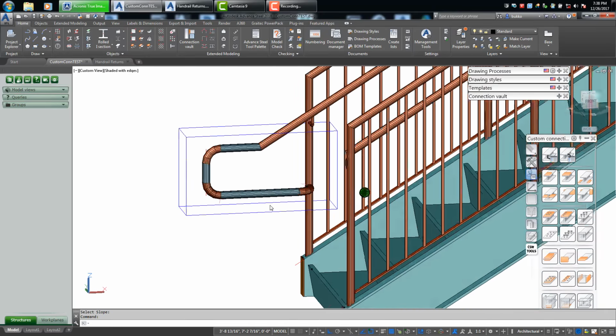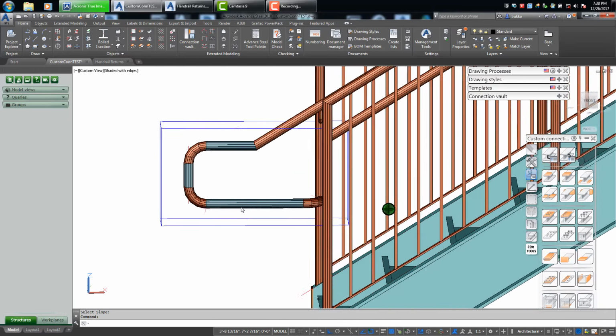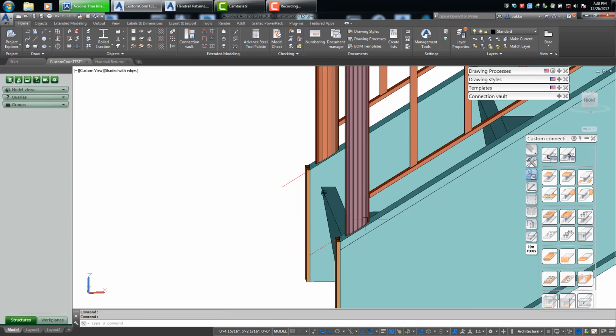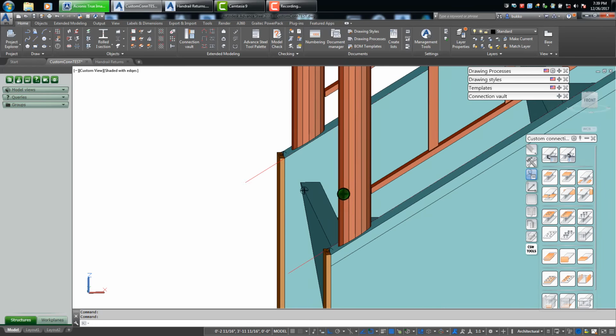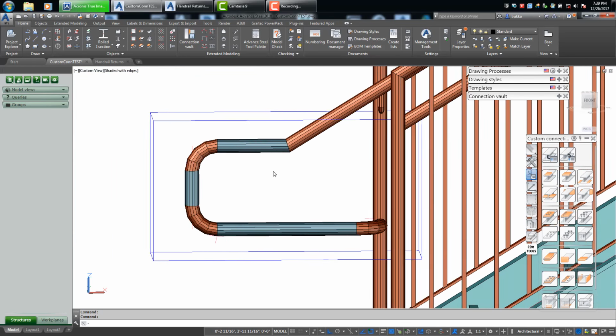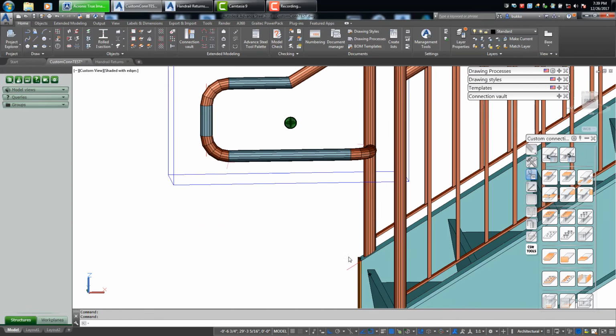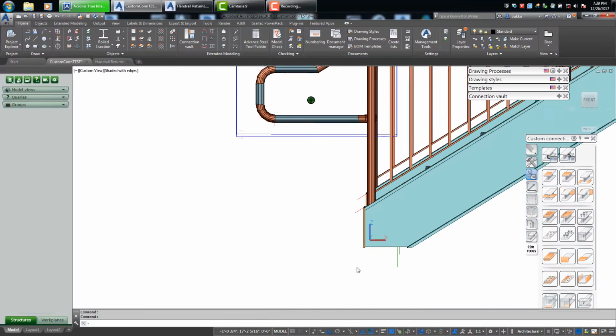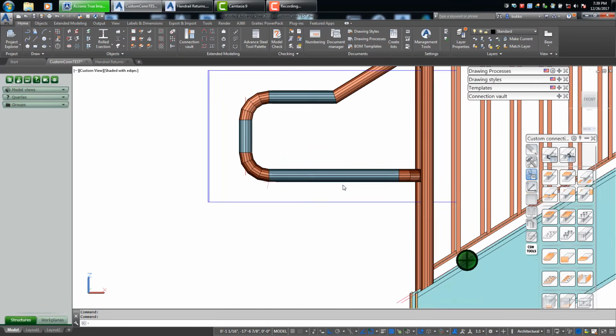And this one, what I've done here when I create these components is I'm using a 12-inch stringer and basically a 1.5 inch offset for the start of the rail here. And so what I'm doing is creating this component to where in a stock situation it would be 35 inches above the ground, and that is 2'11".